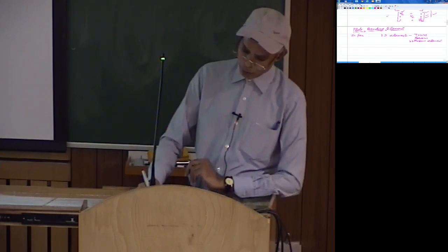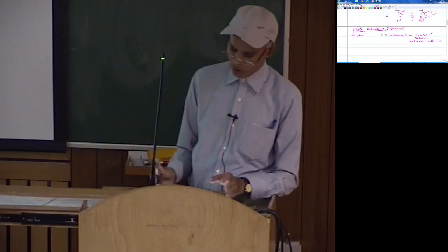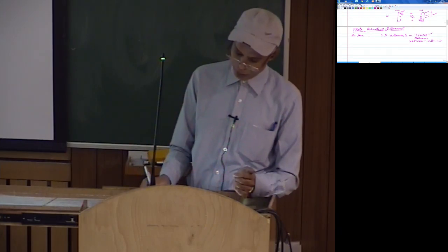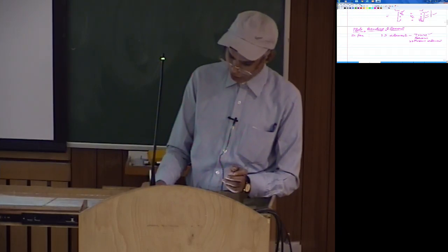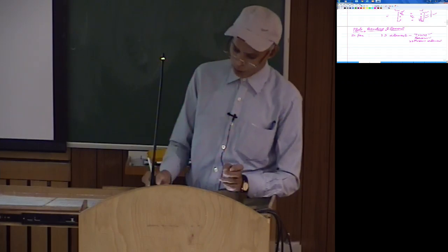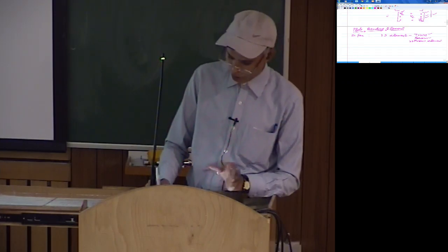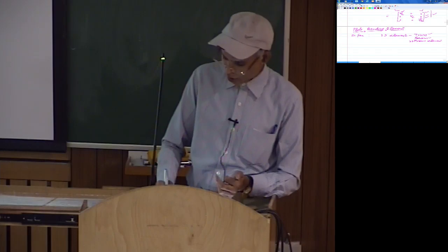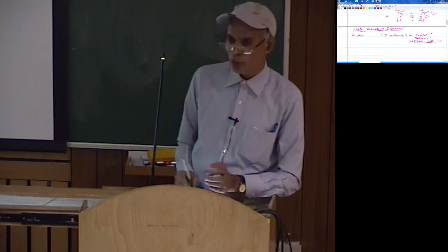So you can model the problems where there are only in-plane loads and the cross-sectional dimensions are much smaller compared to the length, using truss. If there are transverse loads, you use beam. If both transverse and in-plane, I mean axial loads, are there, then you use frame element.